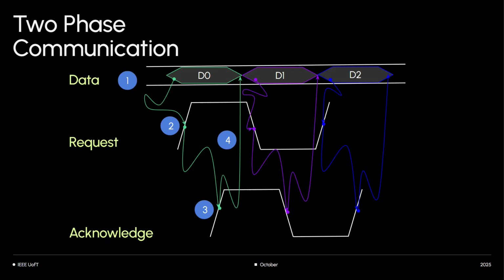And you don't need to wait, like in this two-phase communication variant, for this to come back down, because each of these lines coming back down is an event again by itself, okay? So you have the next data, you place it, the sender places it, waits for it to nicely get to the other end of the receiver, and then signifies to the receiver that, hey, it's time for you to latch it in, and then sends an event, and the receiver receives it, clocks it in.